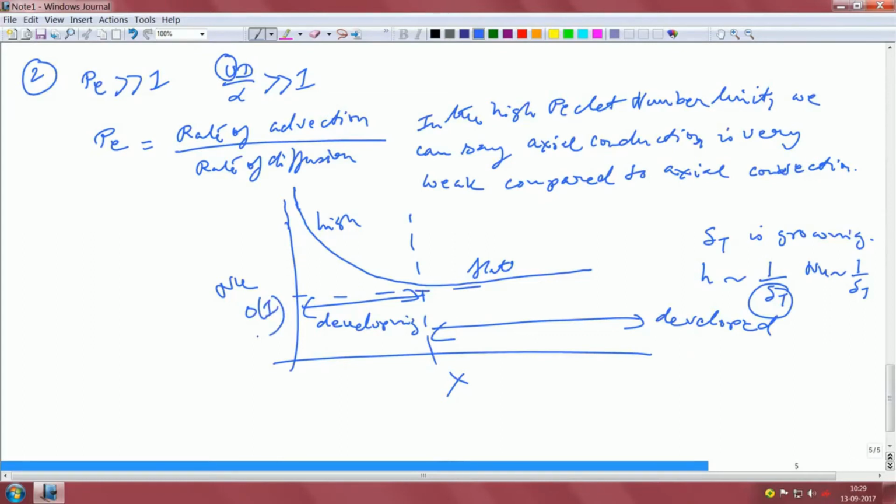So, anywhere between 1 to 10, something like that, it will be your Nusselt number value regardless of whatever you do. It is very high initially, then asymptotes and becomes this flat line, which is not a function of x anymore in the fully developed regime. So, that is a very important conclusion: this is the region of high Nusselt number, and this is the region of constant Nusselt number or heat transfer coefficient.